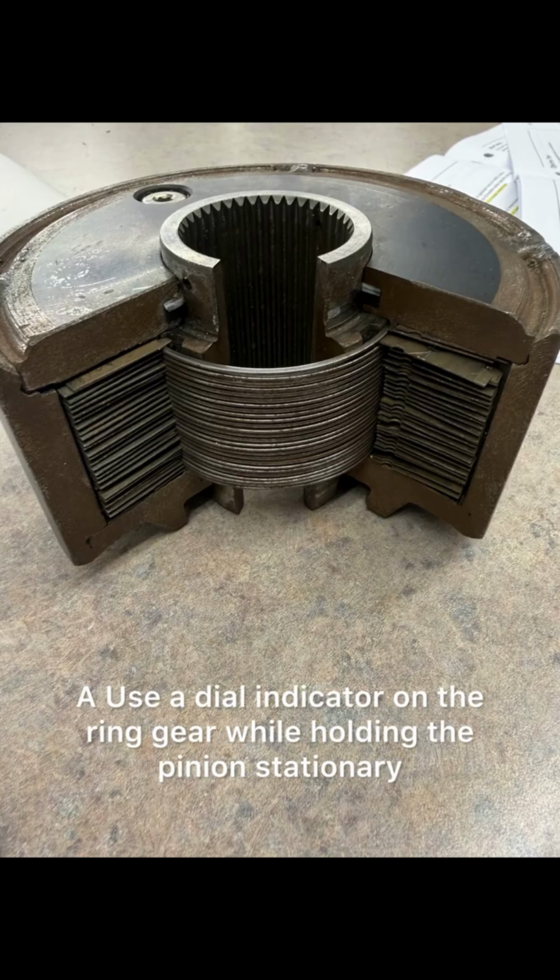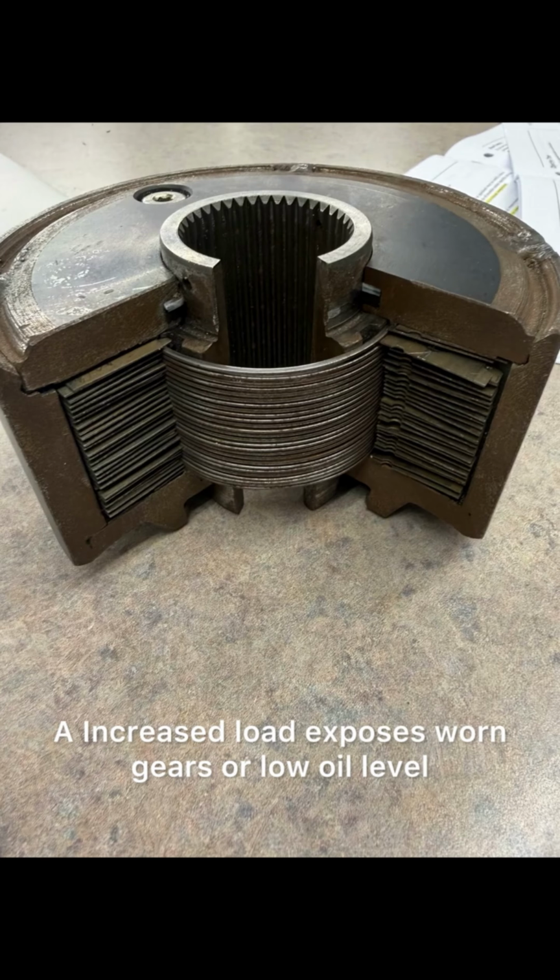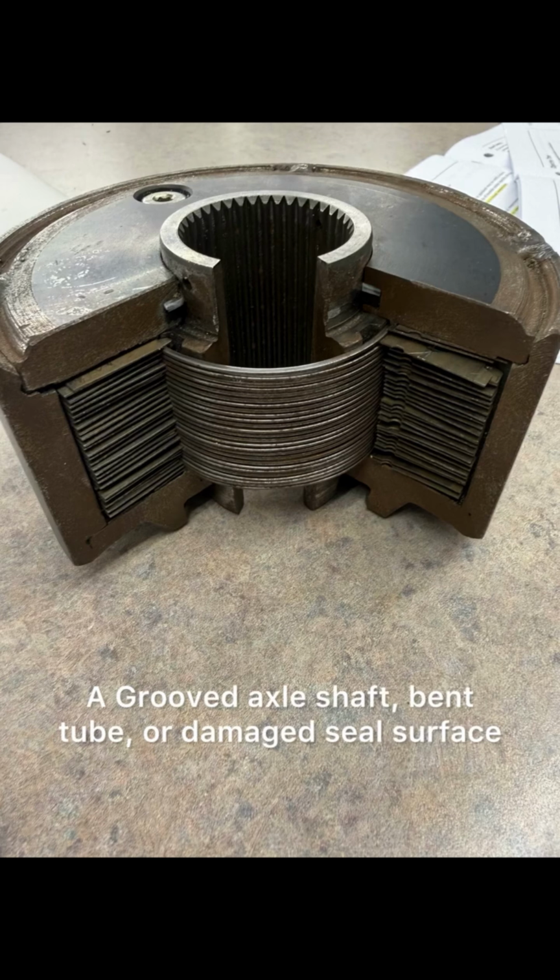A dry or worn slip yoke on drive shaft. 29. Why is the differential noisy only when towing? A. Increased load exposes worn gears or low oil level. 30. Why would a new axle seal leak again after 1 week? A grooved axle shaft, bent tube, or damaged seal surface.